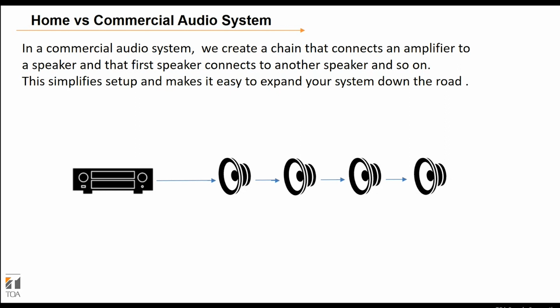So we tend to create a chain that connects an amplifier to the speakers, and that first speaker connects to another speaker, and so on and so on. So they're just basically daisy chained together, so we don't have to worry about having multiple different speaker wire runs. So this simplifies the setup, makes it easy to expand the system down the road.